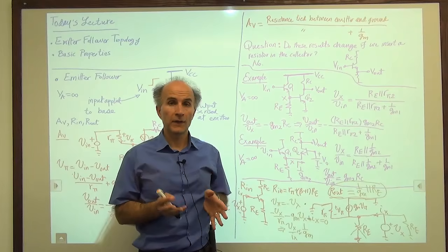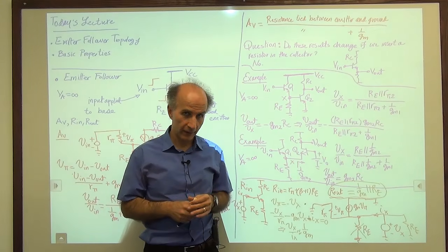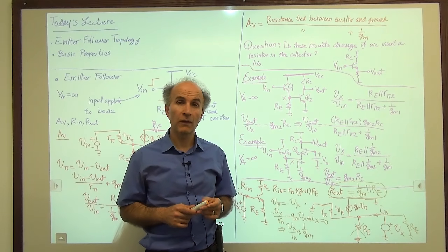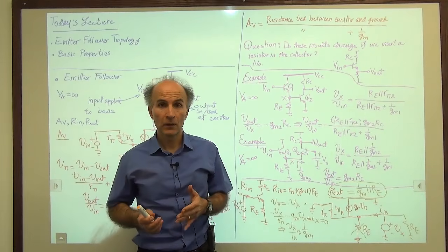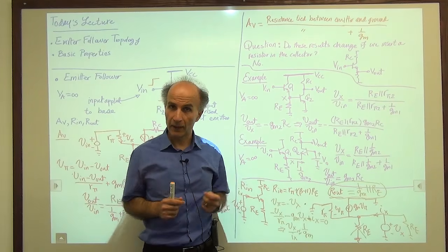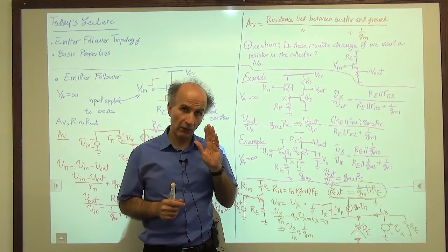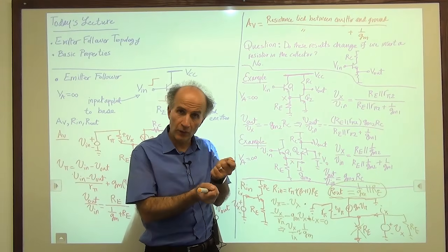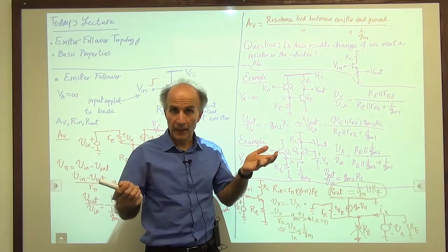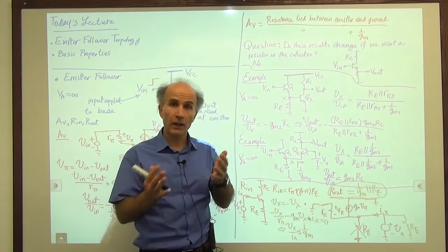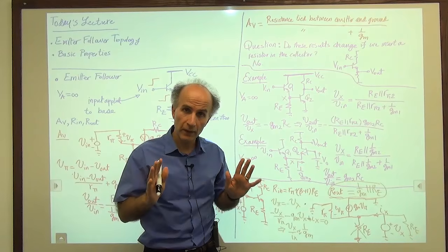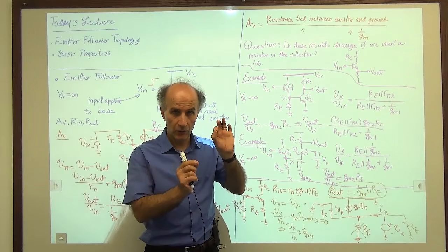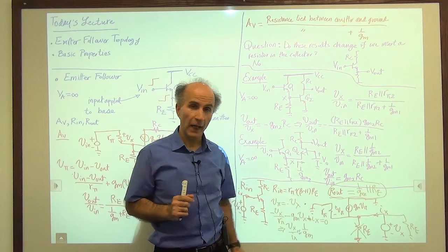So that's also interesting. That points to yet another important fact. If we are interested in the output resistance of a circuit, we don't know where the input is. In fact, sometimes we don't even know whether this is an output node or an input node. And that's perfectly fine. So long as we do the calculations correctly, we set all the independent sources to 0, and we're finding the impedance between two nodes, that impedance is some amount. And it doesn't matter whether you want to call it an output impedance or an input impedance. The only golden rule is to set all independent sources to 0 when we are calculating the impedance between two nodes. All right, and that's why these two happen to be the same.